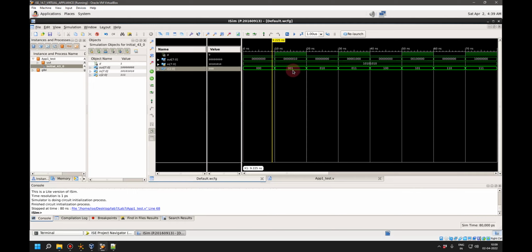If I give a control 0 0 1 out here, D will be 1 because I am selecting the second bit, and the second bit of the input I have given as 1. So that is why this is 1 out here, and in the output also the second bit is 1, right? And if I give the next control signal 0 1 0, obviously the third bit is 0 here, so D is 0 and the output everything is 0 out here. So this 1 0 1 0 1 0 1 0 is being reflected here also.